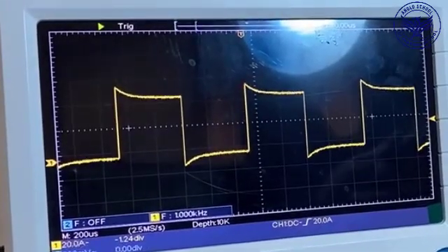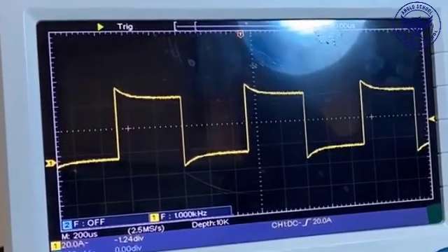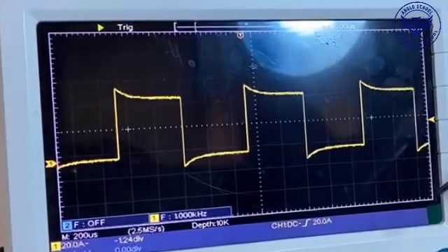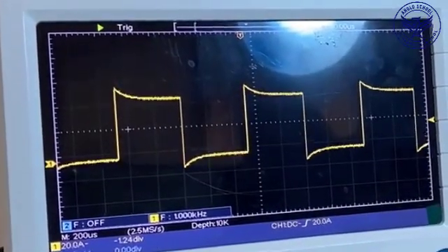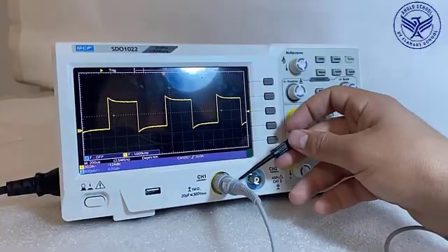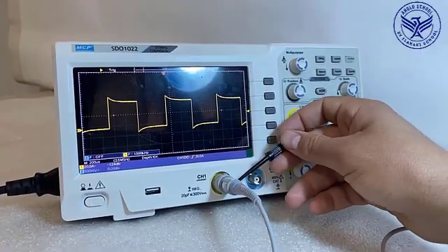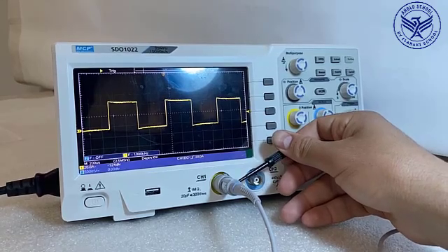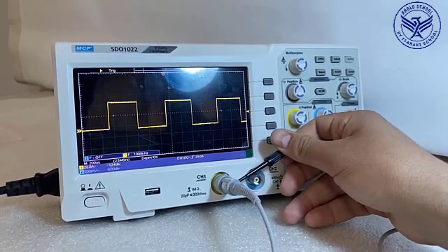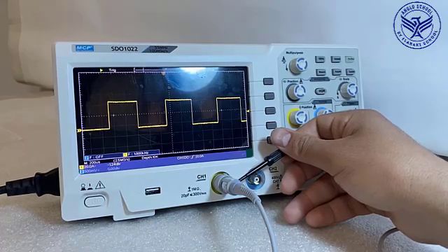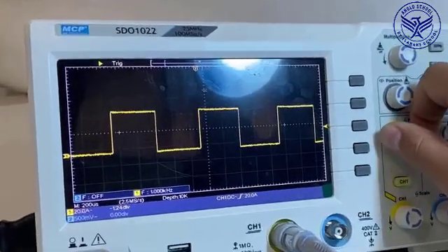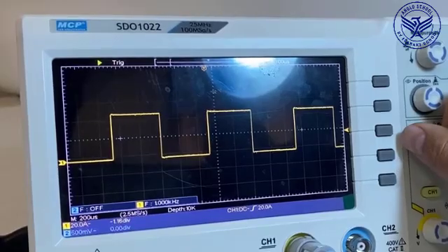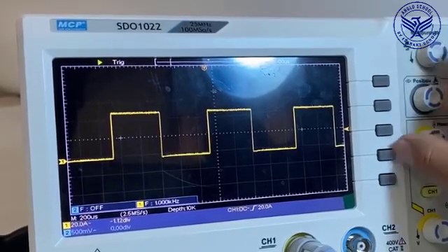Now, these highs and lows should appear completely flat, as we assume the scope is outputting a near-perfect square wave. If not, it's because the compensation capacitor in the probe hasn't been tuned, so we're actually measuring the signal incorrectly. Using a tiny flathead screwdriver, adjust the screw head in the probe until the square wave has straight edges. Note that some probes have the compensation adjustment screw near the probe's plug instead.